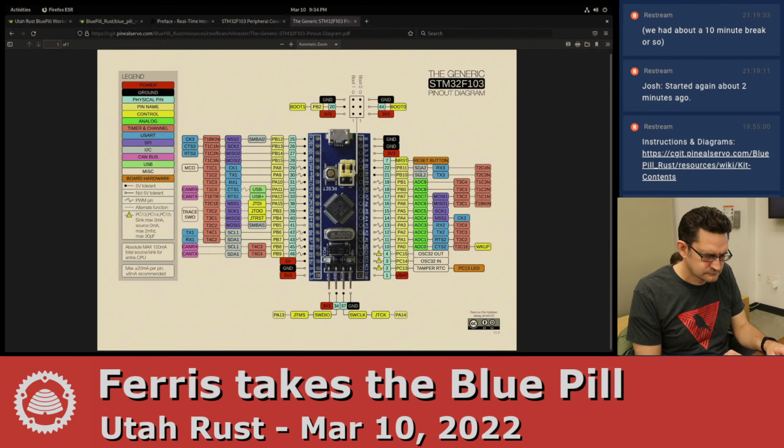And then the display, what was the voltage on this? It's 3.3 volts. 3.3 volts and ground. Just next to the data, there's the reset line, and then there's 3.3 volts, and then there's ground. So clock, data, skip a pin, 3.3, and ground.